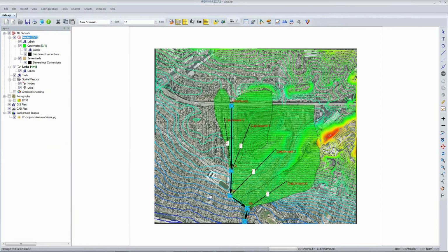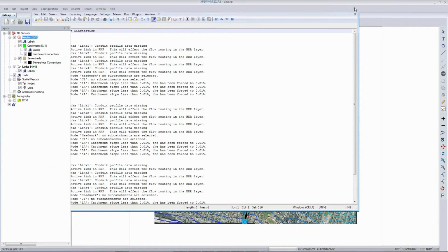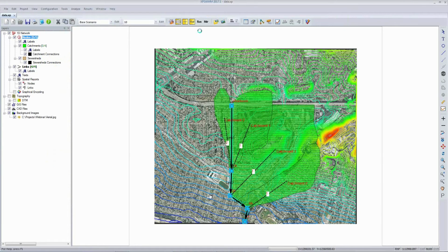Yes, in the runoff mode, when I imported, well, let's see, what? Yes, I'm missing a couple of nodes not active. There we go. I just pressed the plus on the keyboard. Well, what else am I missing? Yes, in the runoff mode, here I am in runoff. I need to make sure all of my links are inactive in runoff, and then I'll be able to solve.